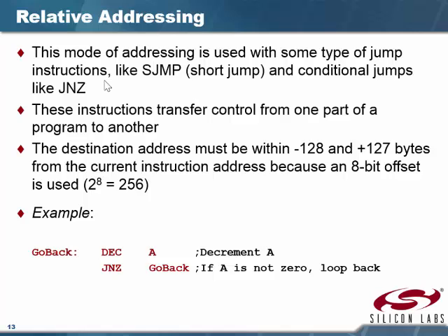If that doesn't work, you change it to a long jump. This is a limitation of this processor. You won't address it in this class very much, but it creates a bit of a headache in that the conditional jumps are all short jumps, which means we can only jump ahead or behind about 128 bytes.